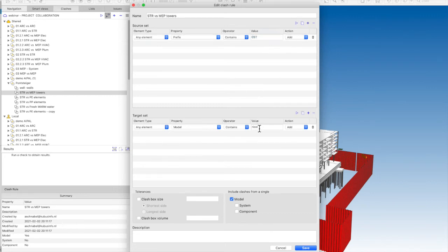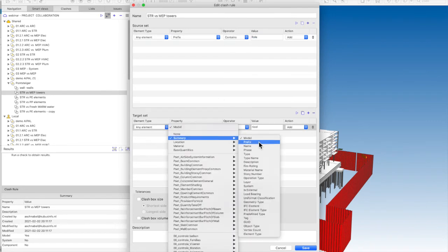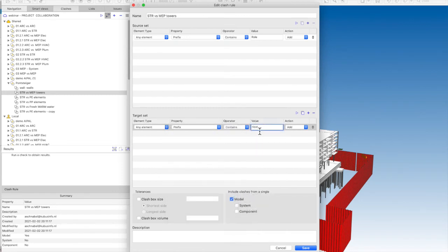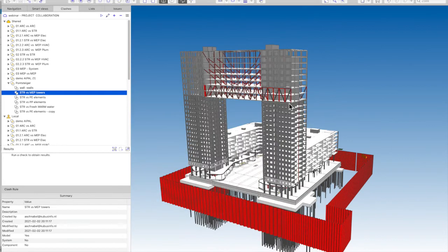And if you have a definition beforehand that there are some prefixes to be used all the time, like role and performance, you know that if I use these two words, all these rules do work. So I can have a role versus performance prefix check, and it doesn't matter which model I use as long as I give them those prefixes and my clash rules work.